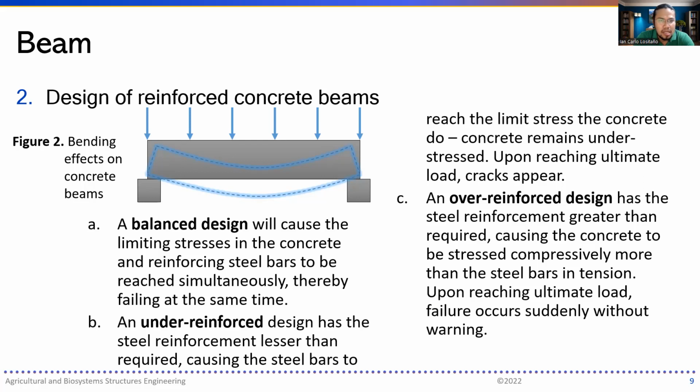A balanced design for concrete beams is that we have the limiting stresses in the concrete and the reinforcing steel bars reached simultaneously, thus failing at the same time.